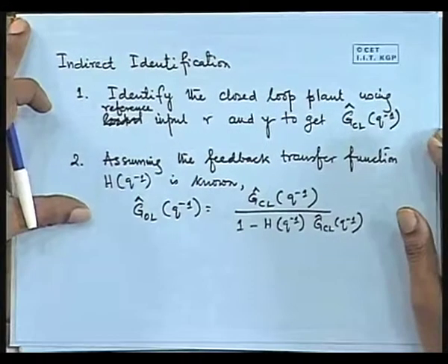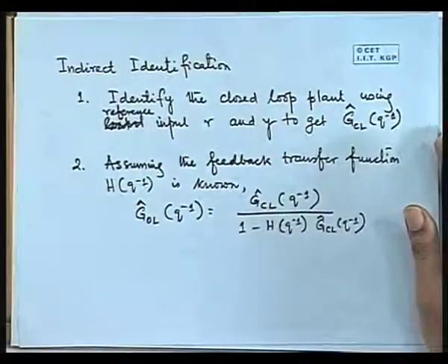So how do we identify? If you ensure that, then there is no problem. Closed loop identification has two problems. One problem is that generally the error will tend to get correlated with the data vector. That will give you some parameter errors. That problem you can solve by choosing various mechanisms, like having a longer model structure or having an instrumental variable. You have to solve that problem if the data vector tends to be correlated with the noise.